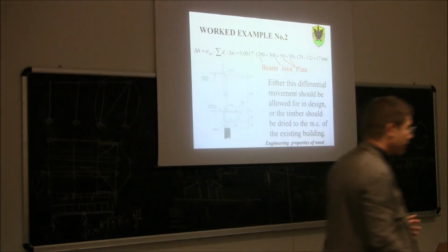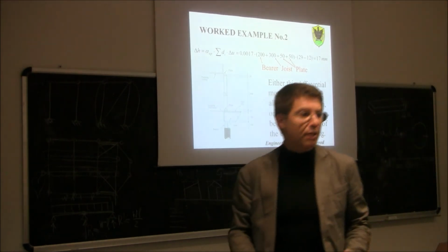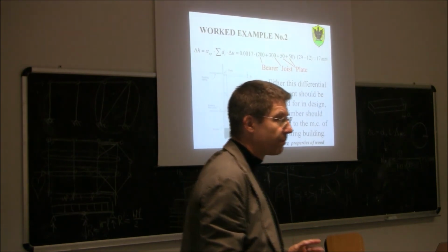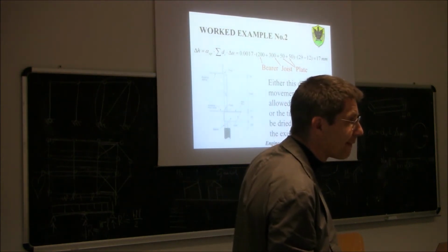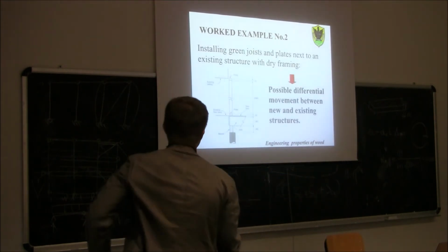In the end, we can expect that if we put this timber extension flushed with the reinforced concrete one, so the same level, later, after some months, I can expect it to have a step of a couple of centimeters. Okay? If I install the wood as a green wood. Instead, if I dry the wood, no problem at all. Okay? In Italian, why we choose the moisture dilation coefficient equal to 0.0017? Yes, in italiano.